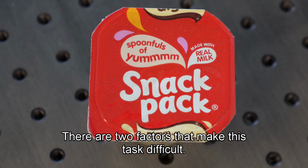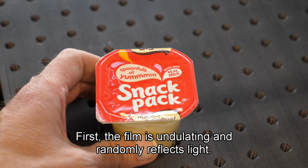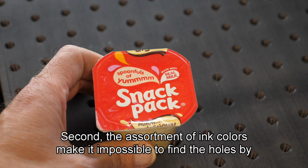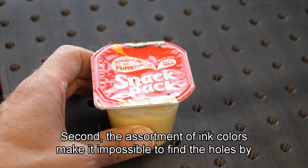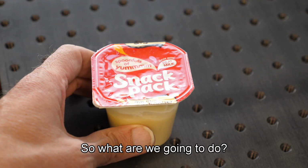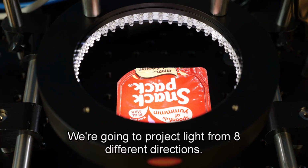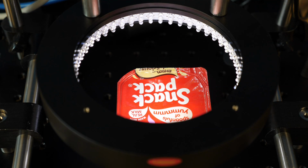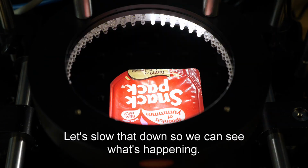There are 2 factors that make this task difficult. First, the film is undulating and randomly reflects light. Second, the assortment of ink colors make it impossible to find the holes by just binarizing the image. So what are we going to do? We're going to project light from 8 different directions. We'll capture 8 images.